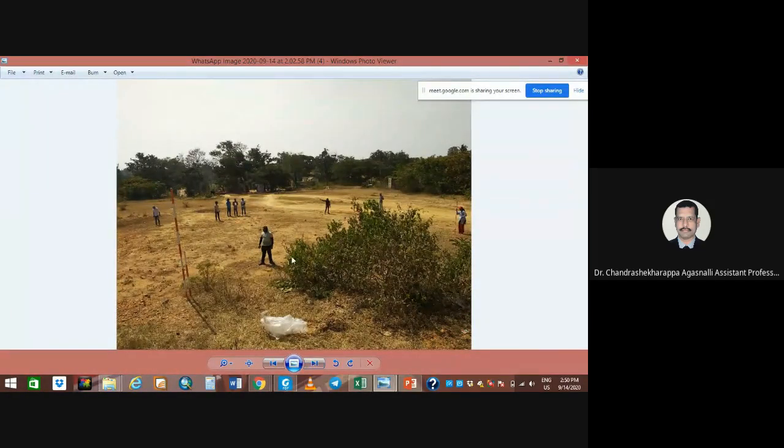Okay. For what purpose are they doing this? Block leveling. Can anybody answer this? For what purpose are we doing the block levelings? We make the block levelings maybe 50-meter based on the availability of the place. Okay, it is not a hard and fast rule. You can do it 500-meter by 500-meter, but that much space is not available in particular areas.